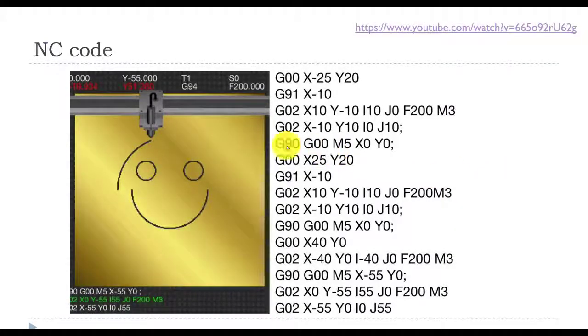And as many of you may know already, NC code stands for numeric control code. And because nowadays we generate and edit a lot of that code using computers, CNC is the common abbreviation, Computer Numeric Control. And to generate something like this, we need this type of code, or G code, to tell the CNC where to move the cutter and at what speed and what time, what position it needs to start and stop at. So the coding is almost like HTML code, the coding that is used to make websites, but the computer needs to read this coding and then it'll translate that for the computer-guided cutter and tell it where to go and what positions.